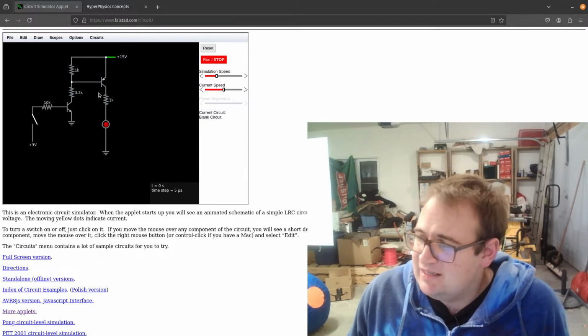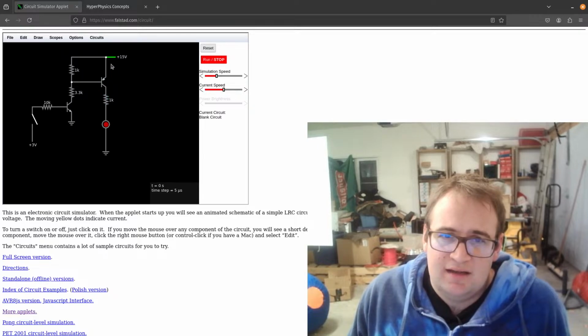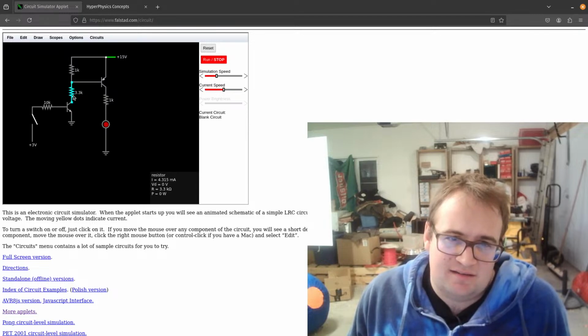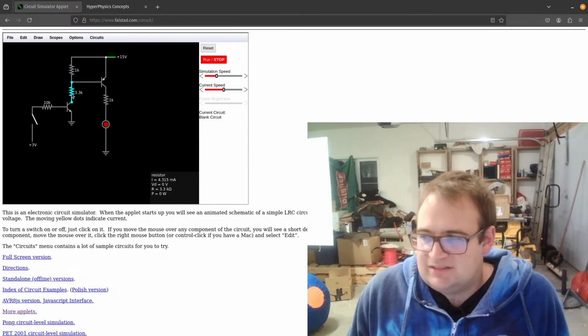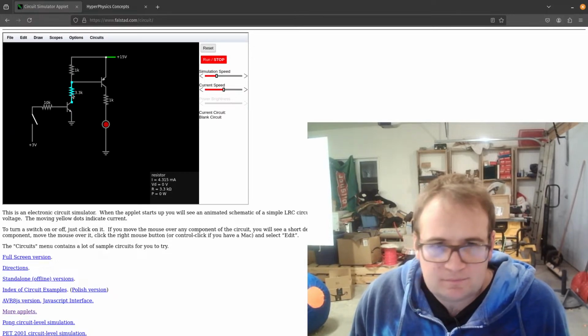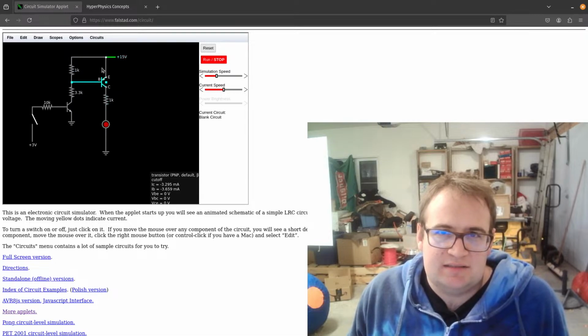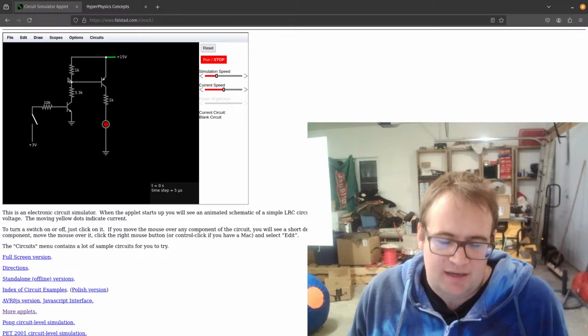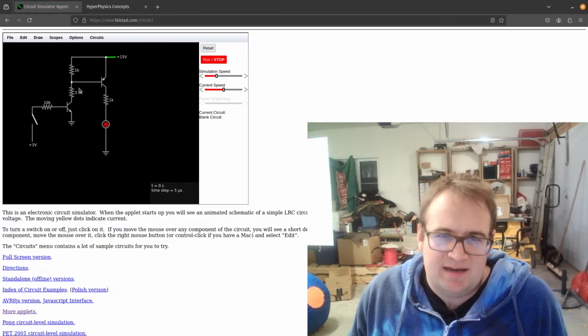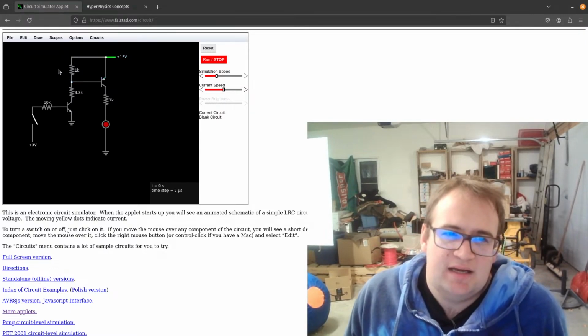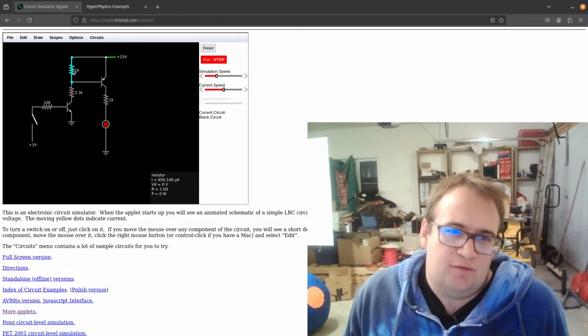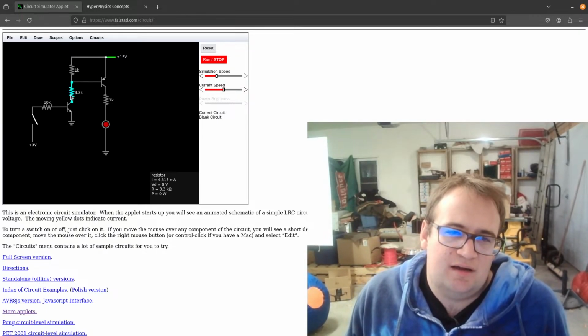I am guessing, if we check this voltage right here, it is going to be 15 volts. Let's just say this is 3K, because I want to do in-the-head math. So, well, then we have 4 parts. So again, let's say that this is 16 volts here. I know it isn't. I'm just trying to do it in my head here. It's easier this way. So that means that 4 volts would be burnt across here. And then 12 volts across here.